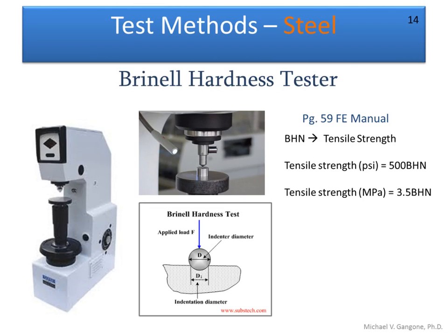But basically what you're doing here is you're taking your specimen, say this little piece of metal that you have here, and you have some plunger that you see right here, and this plunger is applying some load P, and there's a small metal ball that is used on top of that specimen, and you're applying a force, and you're basically going to measure how much area is indented in the metal below from this particular ball as a result of the load P that's being applied.